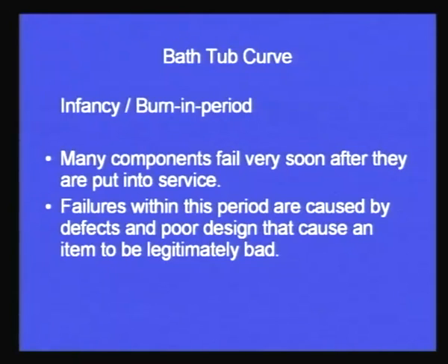So let's now talk about the very first stage, that is the infancy or the burn-in period. So the bathtub curve has three different phases, out of which first one is the infancy or the burn-in period. Many components fail very soon after they are put into service. Why? Because of some wrong design, because of some wrong calculations, or because they are not able to adapt to the environment. So many components fail very soon as they are pressed into service.